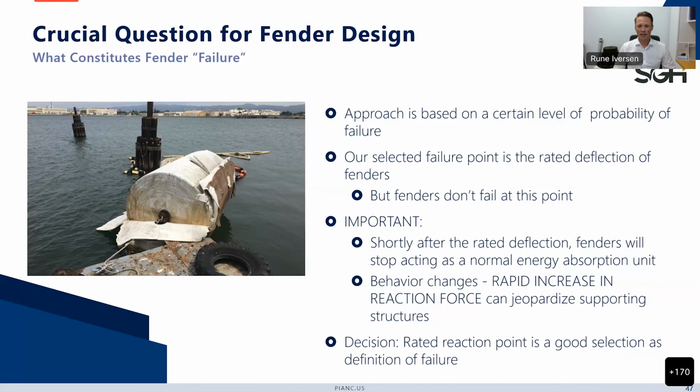Shortly after you reach that rated deflection, most fenders will stop acting as the normal energy absorption unit. The behavior changes, and you will see a rapid increase in reaction force. And that's something that can jeopardize your supporting structures. So it was decided as part of the working group that the rated reaction force is a good selection as a definition of failure. The fender doesn't necessarily fail, but at that point you start jeopardizing the supporting structure.